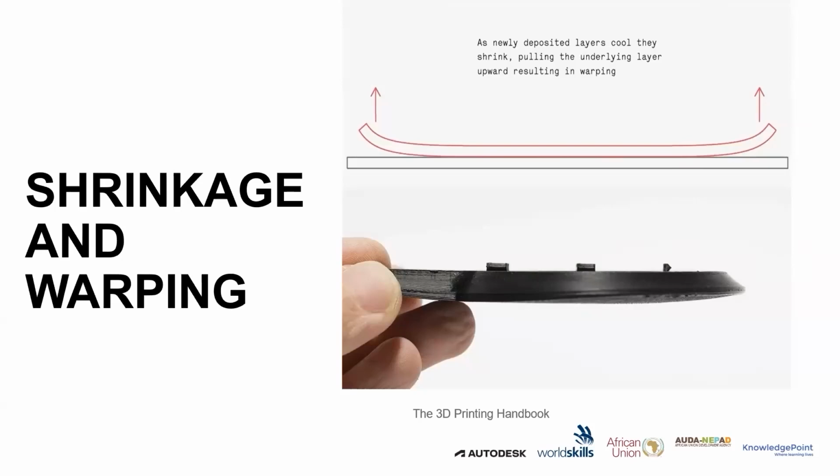Another aspect is that ABS, or maybe PETG and some other filaments, also require an enclosed volume. The enclosure needs to be closed so that there won't be so much interaction with the temperature of the surrounding environment. If you have an enclosed volume, you can keep the temperature in a particular range and not allow the outside to affect the temperature inside around the printing part. So if you're able to have a heated bed and an enclosed volume, that's almost 90% of solving warping.